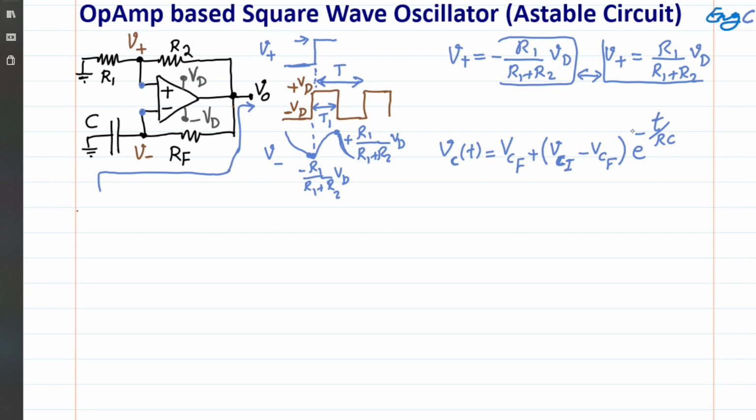Which in this case would be RF C, of course, because the resistor that is related to C is just RF. So let me just clean this up. This resistor needs to be clearly written as RF times C. That's our constant here, the time constant. Now, of course, this is easily obtainable. If you don't want to write this, the easiest way is just writing one simple KCL or KVL here. However you want to do it, it would be super easy.